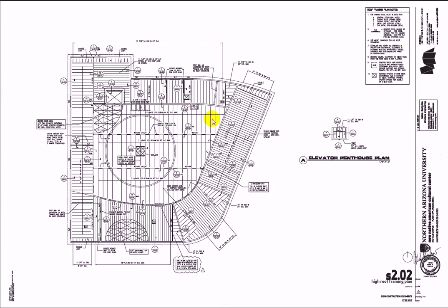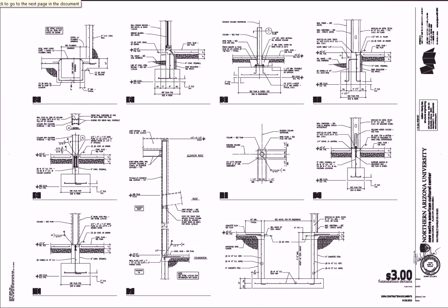I'm not sure what the material is yet. I'm not sure if this is wood, if it's steel, if it's concrete. Not until I zoom in closely can I really tell that. Let's page to the next one. Now we're starting to get into the details. And typically structural drawings are organized in series, like 100s, 200s, 300s, etc. So here we can see the 300 series of the foundation details. That keeps the foundation contractor organized in one spot.